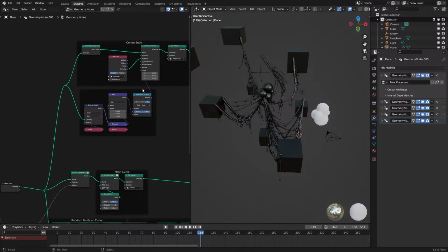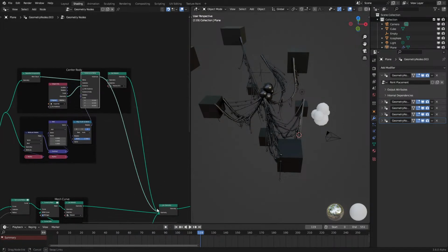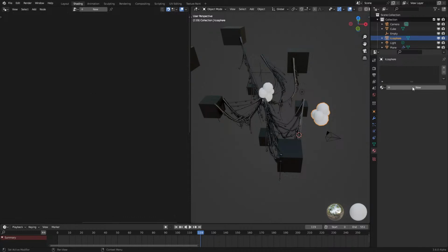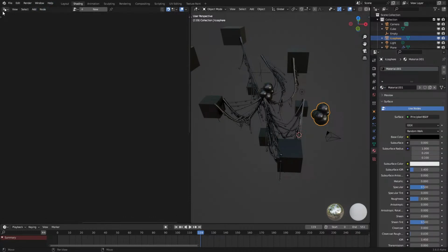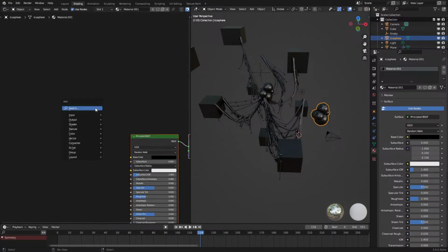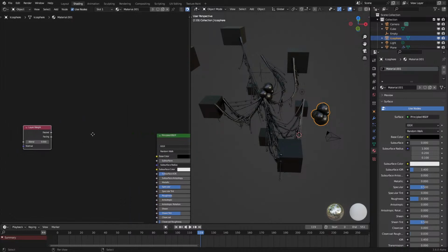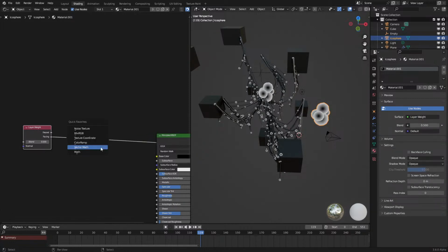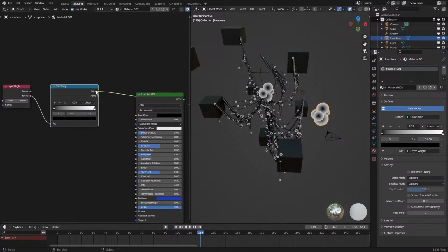Yeah. So let me remove the set material node from here so that I can set it over here. Let me set that to the secondary one because I want to try... let's go into... breathe. I need to remember to breathe. So let's use a layer weight node, just so that I can get that nice normalized Fresnel. Switch between the emission or no emission.